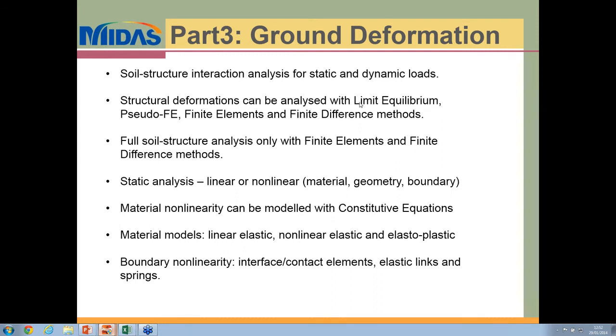But the limit equilibrium solutions are handicapped in a way that they can't give you the deformations within the soil itself. They might give you the deformations and the forces in the structural members, but not in the soil. So to get the full picture in the analysis, you need to perform soil structure interaction analysis either through the finite elements or through the finite difference methods.